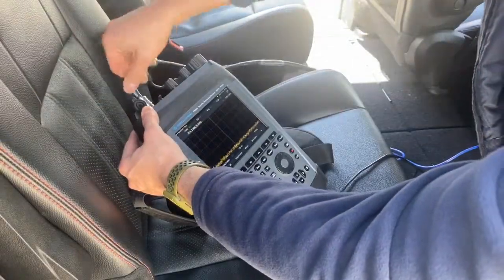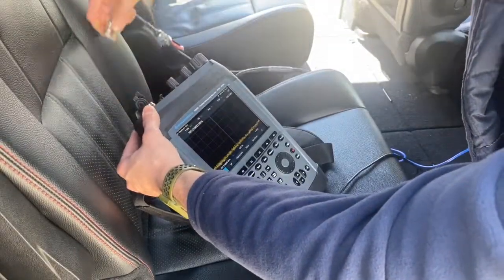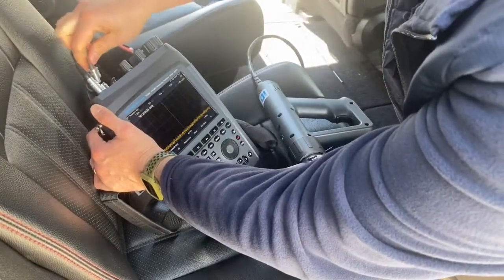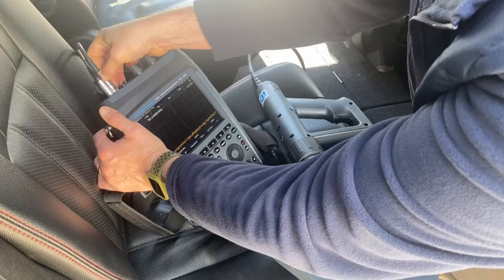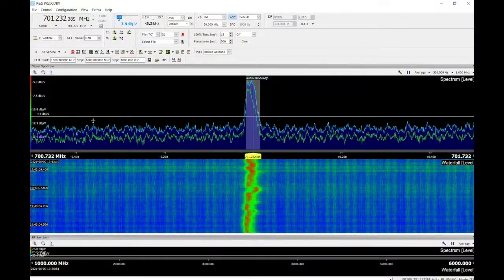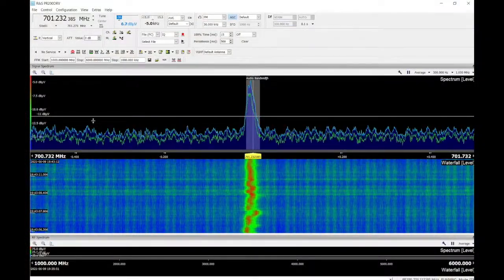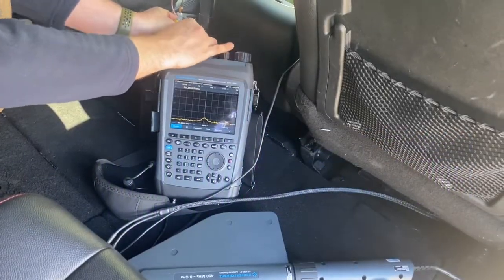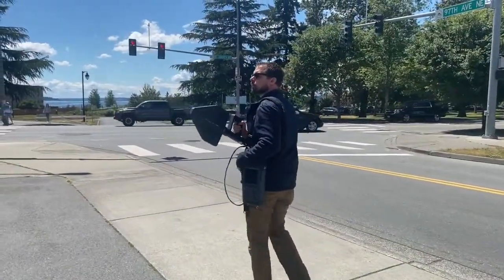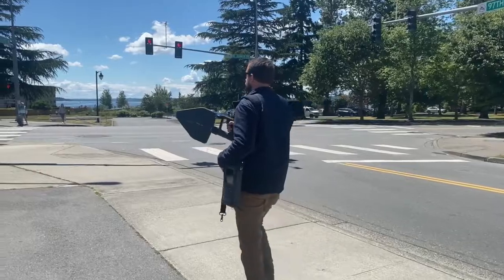Ryan disconnects the PR200 from the mobile locator and connects it to his handheld antenna. He is now ready to hunt for the interference. The PR200 is already set up to track this interference source. The Spectrum Waterfall and Max Hold view provides a very effective visual for the interference signal. Ryan turned on the tone function for an audio indication of the interference while he moves around the area.